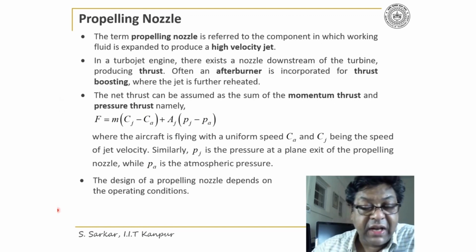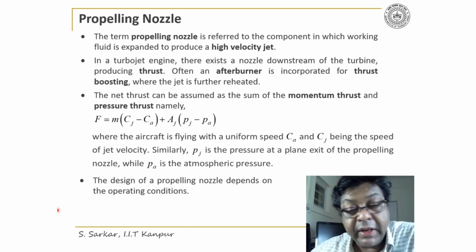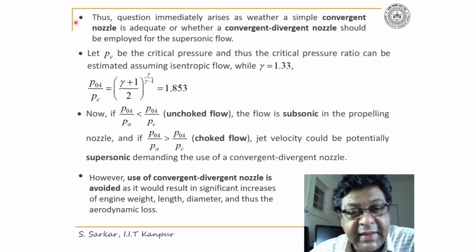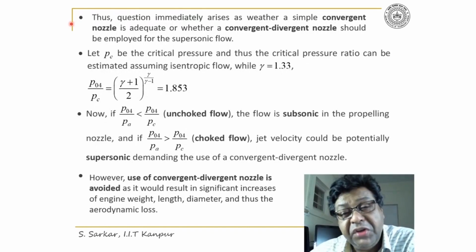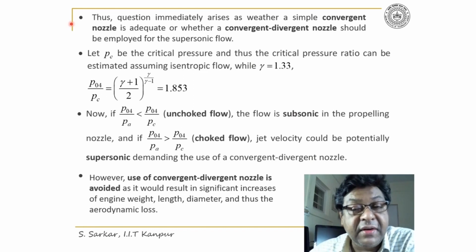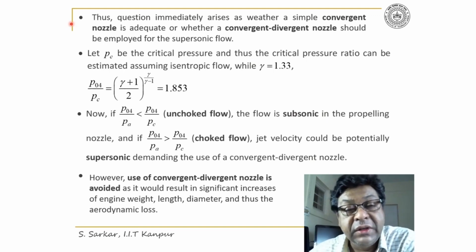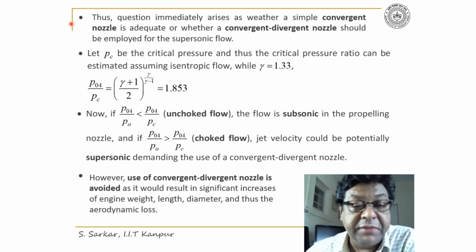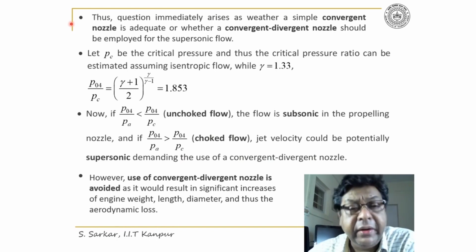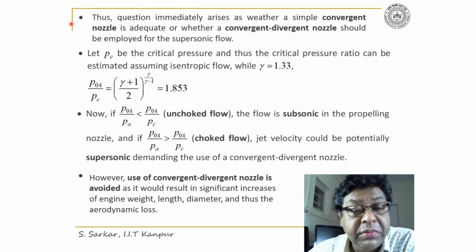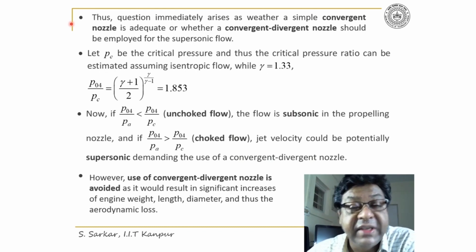Now further I'd like to tell you that the design of a propelling nozzle depends on the operating condition of the flight. Thus, the question immediately arises whether a simple convergent nozzle is adequate or whether a convergent divergent nozzle should be incorporated, particularly for supersonic flow. Here, let me assume the critical pressure Pc.